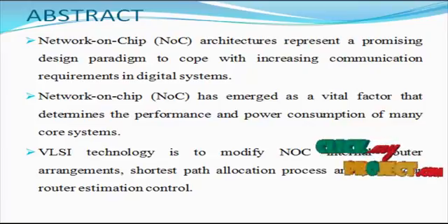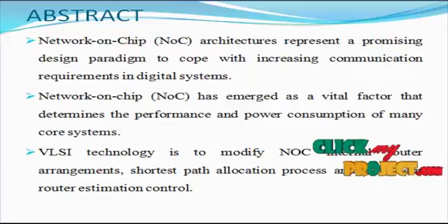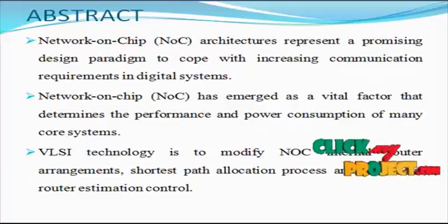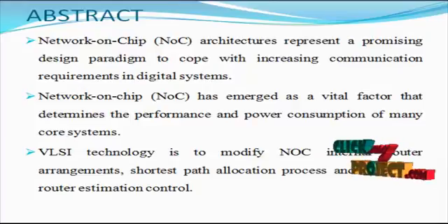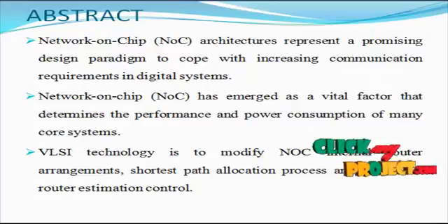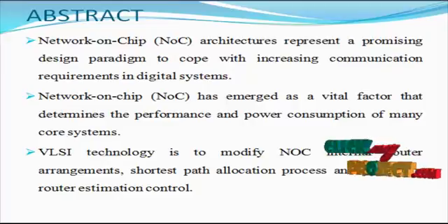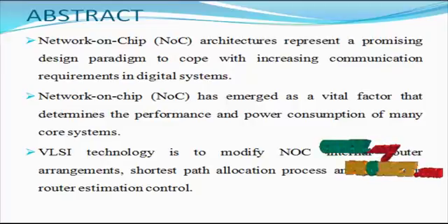With the scaling of 3D IC technology development, 3D system design is becoming the main research trend, especially network on chip, as a novel option for integrated multi-core systems submerged in the 3D tide. 3D NoC can make use of many advantages of current 3D IC, including reduced global wires, decreased end-to-end delay, lower power, increased package density and saved chip area, supporting interconnect design with different CMOS combined in manufacturing technology.